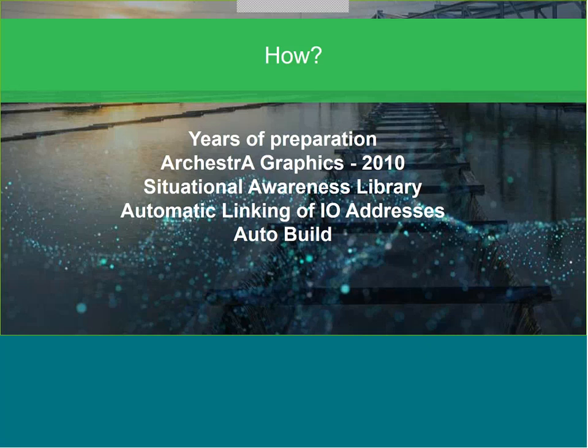They've also introduced something called auto build. Auto build allows you to suck the items out of certain PLCs. At the moment, it only works with Siemens PLCs, but they are going to be doing it with Allen Bradley soon, so we can expect a release on there. What that does is literally suck out all the items and put them all inside a system platform. So if you've got them set up in the same UDT format as in your PLC, it'll create the right structure inside of your system platform environment automatically.